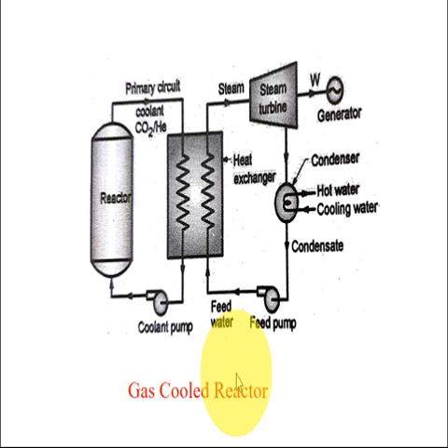So that gas reactor was known as the gas cooled graphite moderated reactor, and this reactor, GCGM, uses natural uranium as a fuel, and the pressure is about 7 bar and temperature is 336 degrees Celsius.